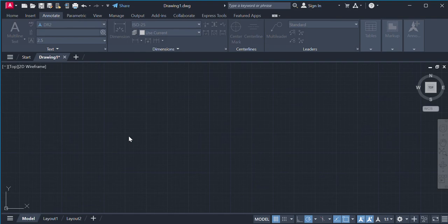Then next you can go to the text placement. Just make sure it's vertically above. So I just want to show you the difference. If you said vertically centered, it is directly in the center of your dimension. Kind of interrupts that line, which sometimes looks a bit untidy. Then horizontal, you can say centered. If you said closer to extension line 1 or 2, then it moves a bit closer to one of the lines. But you can choose centered. Then view direction, if you said right to left, obviously it changes what you're doing. But remember that in our standard, we read from left to right.